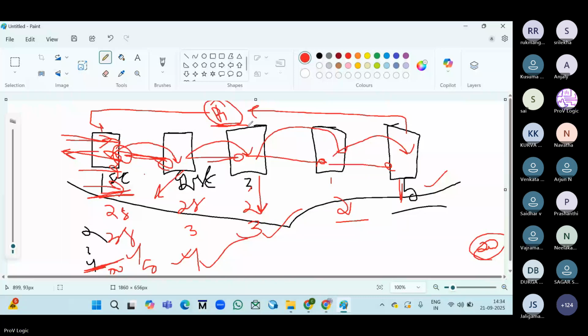Yes, ma'am. Everything is dependent. That's why, here, once R1 is available at this stage, we don't need to wait for all 5 stages. If it is getting R1 here, the next stage will also immediately reflect the value. That's exactly what pipeline is. We don't need to go through the first stage for R1. We don't need to start from the first stage. Did you get the point?